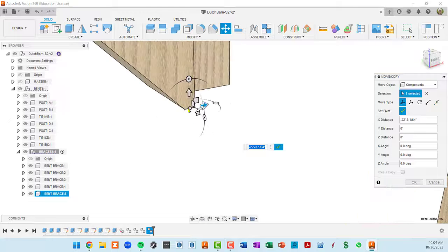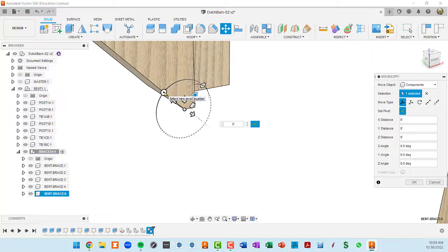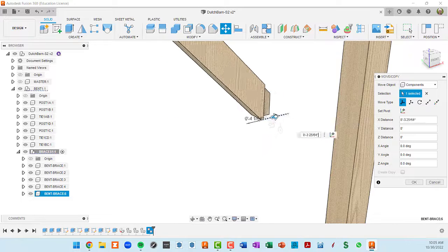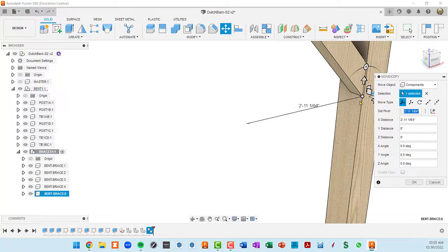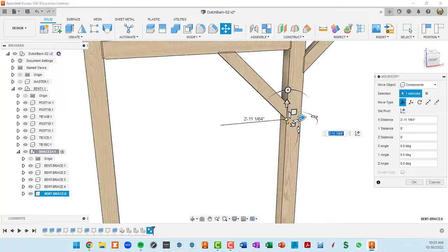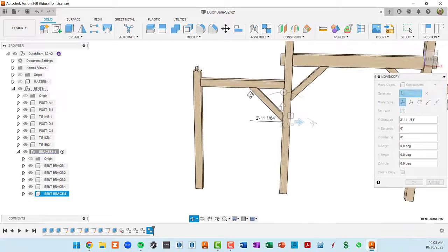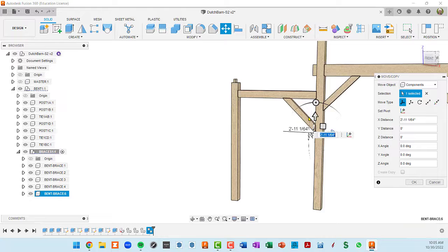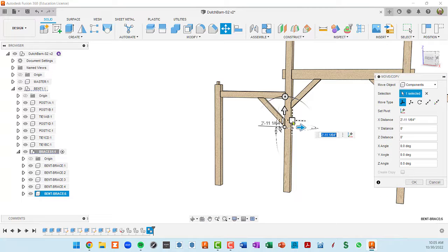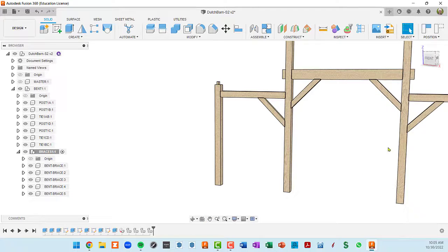It's a little tricky getting this pivot in the right spot, but okay, my arrows are not up, so I'm going to go to 45 degrees, type in -45, and then click on the green check mark, and then move it horizontally, select that surface that is embedded by 1/2 inch. And since we started from this right-hand part of the bent, I don't have to do a vertical move here, so I can just do an OK.